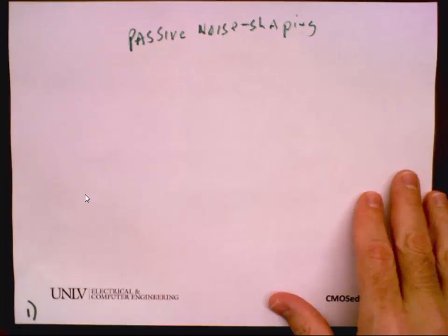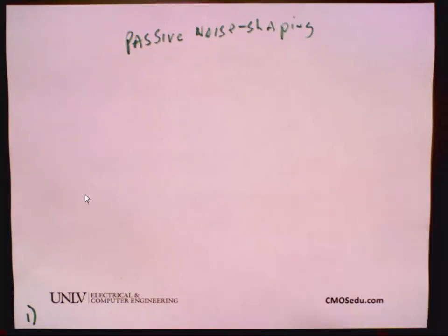You're going to have to simulate for a while, shouldn't be bad, but it should give you the basic idea. And then you can use the output of the DAC to have the signal and the quantization noise to do the FFT on that, instead of adding another DAC. So the signal you fed back, the output of the DAC, you can use to show that. Does everybody follow that? Okay.